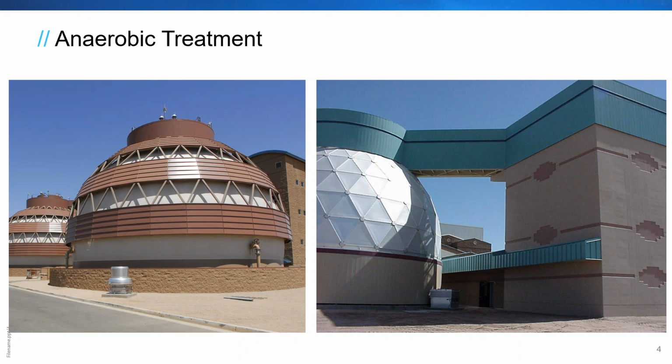Typically, though, at larger facilities because of the scale and need for the solids to make this technology viable. There's been a lot of good studies done over the years that, depending on where you're at in the world, location-wise, for power and whatnot, and temperature, show what makes sense for putting in anaerobic digestion. I've seen numbers anywhere from 4 to 10 MGD as a bottom level for anaerobic digestion.